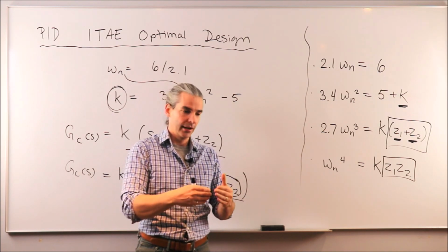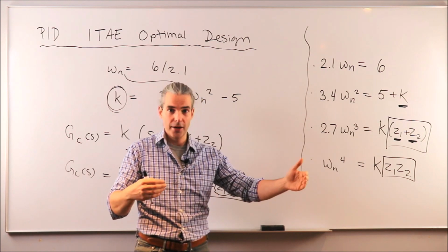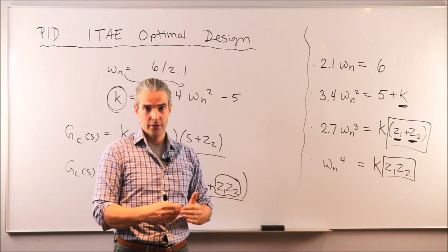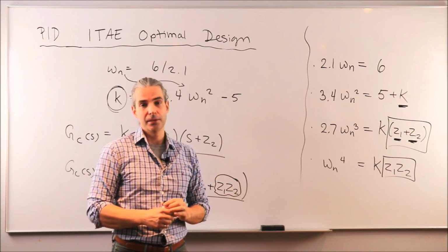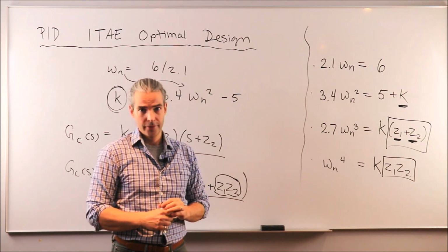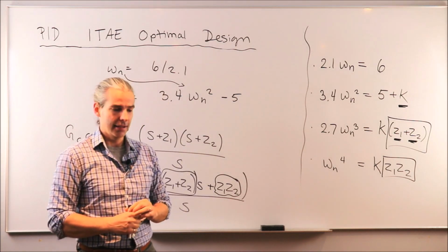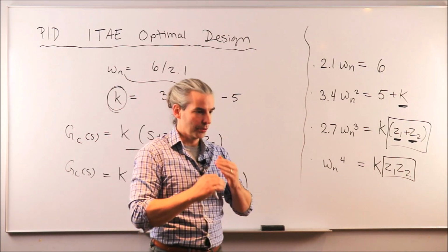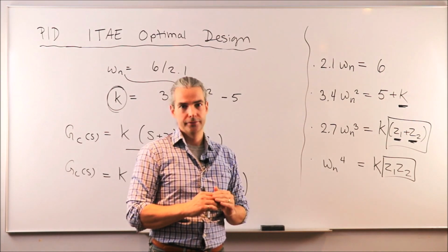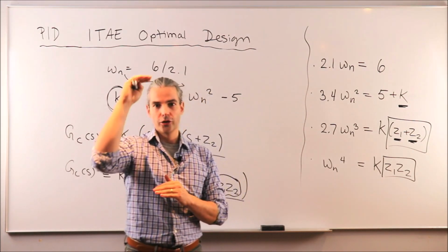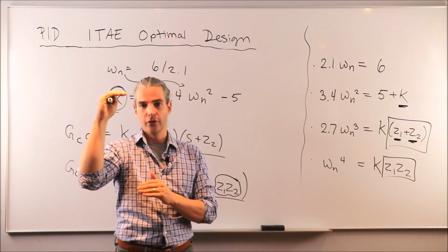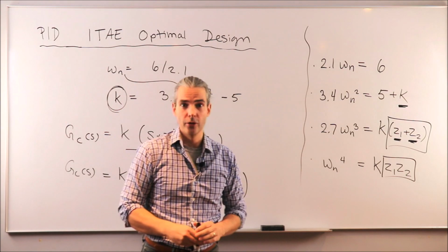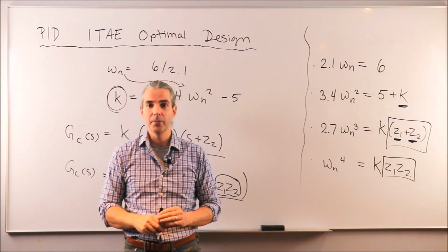So because it penalizes long-lasting trajectory tracking errors, we can expect a relatively short settling time, yet probably at the expense of a larger overshoot, because the ITAE, again, aims at minimizing responses that would take a long time to converge. So that's what it would do. A large overshoot is the price to pay for rapid settling time. So that's what we expect. Yet, let's confirm that together by looking at the Matlab implementation of it.